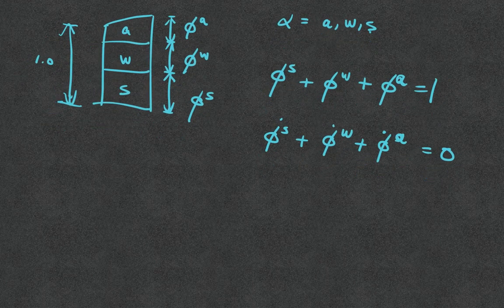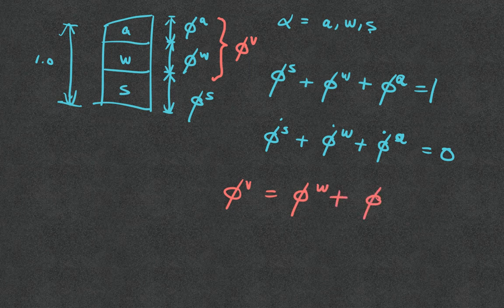Now here, a lot of times for convenience, we will sum these two terms together, and like what we did before, we will call it porosity. So the porosity, sometimes we will write something like this, V standing for the void space, and then we will have this equal to the sum of the volume fraction of the air and the volume fraction of the water.